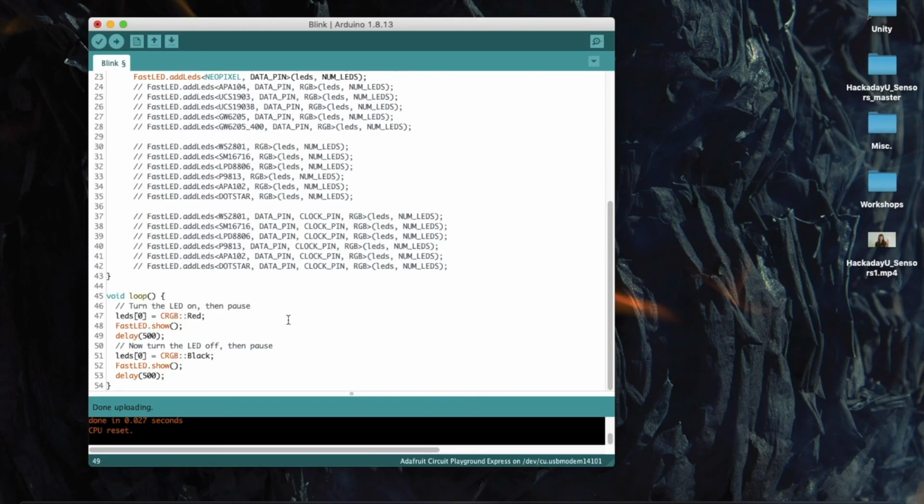These 3 lines represent the fundamentals of any FastLED sketch: code that changes the values in the LEDs array, a FastLED.show call, and some timing code. At its ordinary speed, the Arduino operates much too fast for humans to perceive, so we need a way to change our lights more slowly. Note that delay is not the way you should do this in non-demo code. We'll explain a better way in the next class.